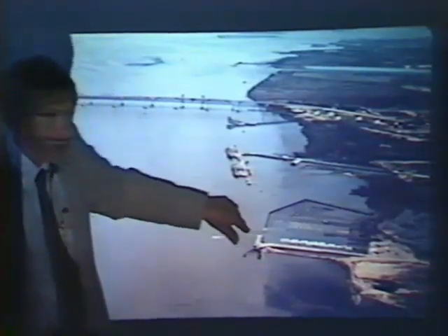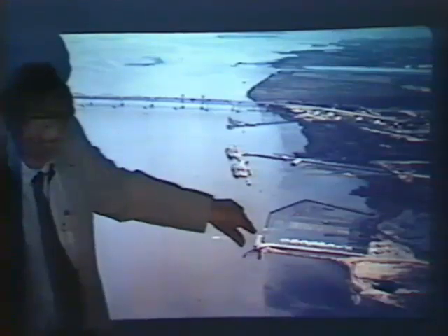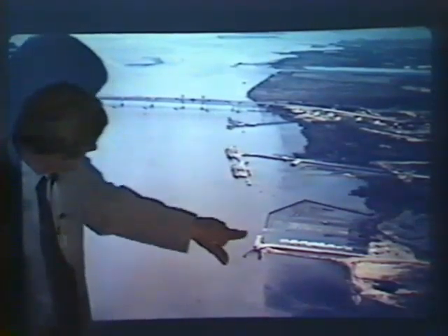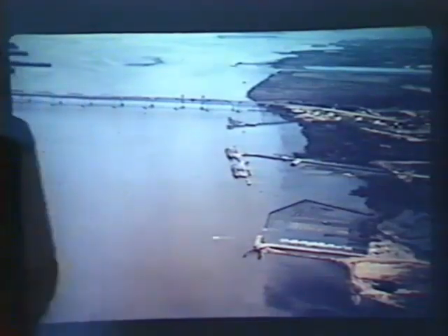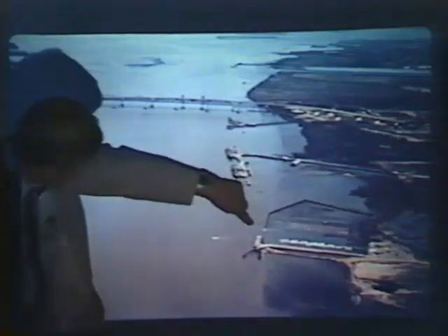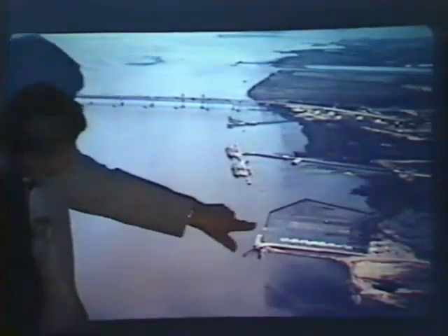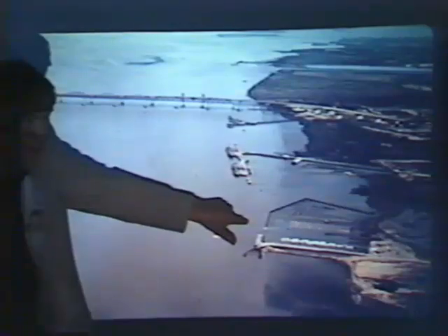To minimize that, all you can do is minimize the amount of sediment that comes in. Now, one thing you can do often is to extend the entrance out to deeper water where the suspended solids are lower. And there's a harbor over on the other side that we did that on. And that does cut down the sedimentation rate. The principle, though, is keep the sediment out as best you can.